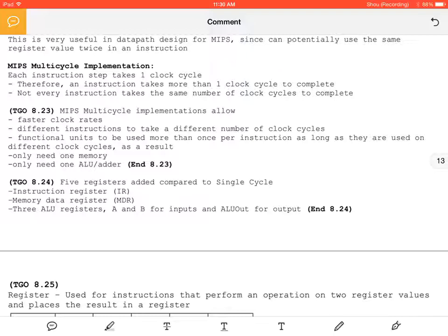But in pipelining, you have to just wait while the data memory stage is being done, right? So that becomes problematic. If you're in a bind where you need to improve performance, but you have area constraints, this concept that I'm going to introduce here, the MIPS multi-cycle data path, is actually a very good compromise. Remember, design principles: good design requires good compromise.